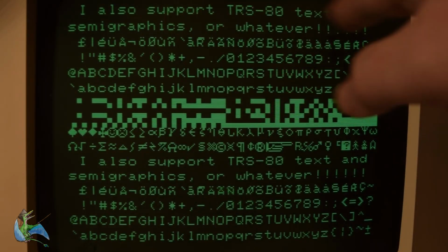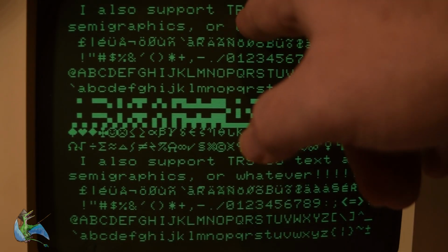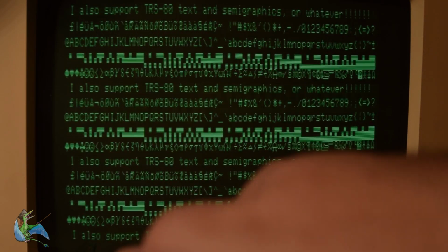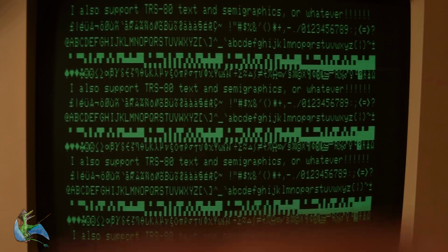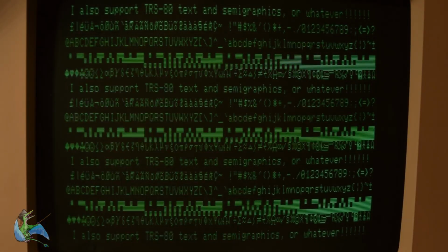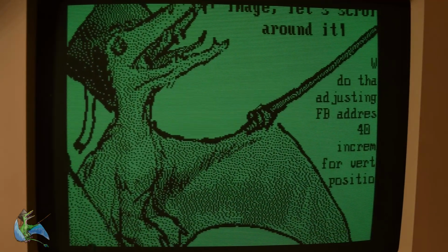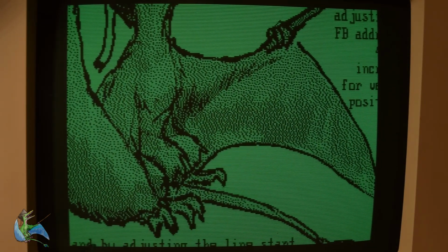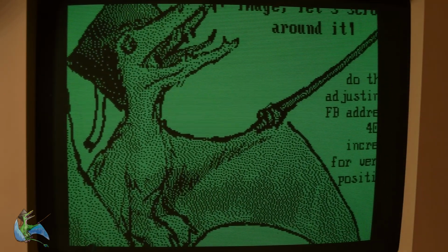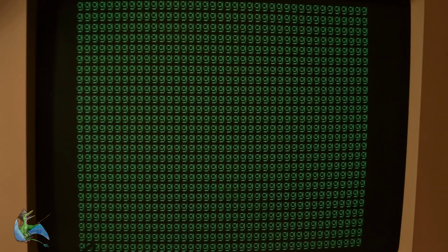It reads the byte, feeds it back around, and then gets the ROM character glyph. When it's doing the pictures, there's simply one spot in ROM where I mentioned that we could just put the numbers 0 through 255 in a row. That's what it's hitting. In theory, you could do some special effects, like dissolves, where you change that translation table and it would fade or reverse the text.